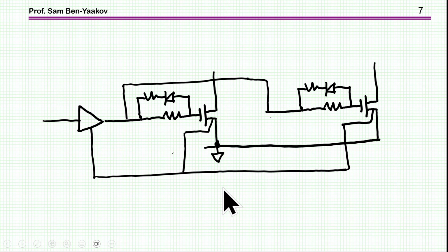The first one is when paralleling transistors. To get higher current, higher power, you usually parallel transistors. So in this case, the simple connection will be you have a driver, and then the low side will be connected to the Kelvin connection. And then you have of course the gate signal coming here and then coming here.